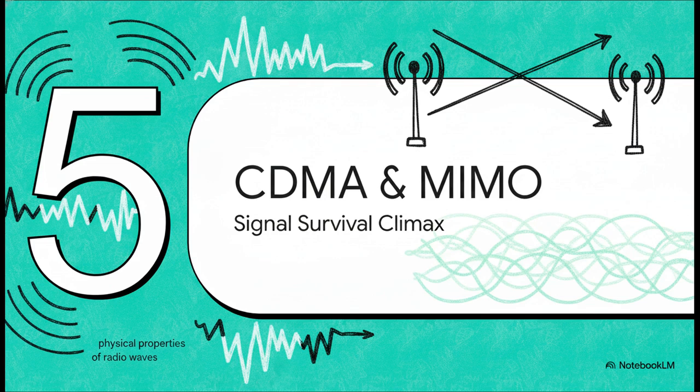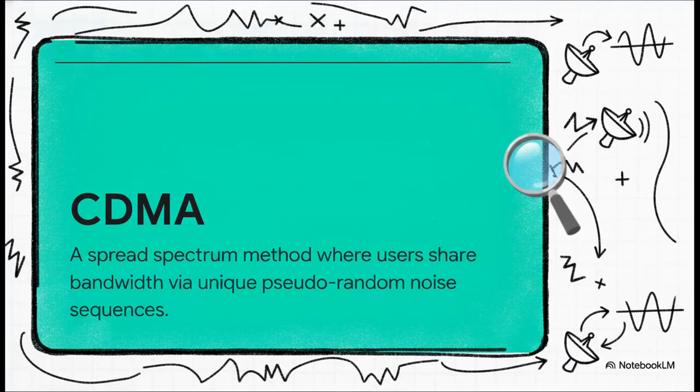Section 5. Advanced Wireless, CDMA and MIMO, the climax of signal survival. Now we reach the absolute cutting edge. This is where engineers got wildly creative with the physical properties of radio waves. First up is CDMA, or Code Division Multiple Access. Remember our highway analogy? TDM takes turns, FDM uses separate lanes. Well, CDMA throws the highway concept completely out of the window. It is a spread spectrum technique where everyone transmits at the exact same time using the entire frequency band.